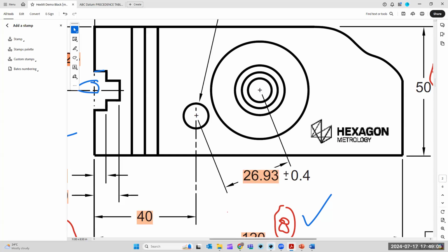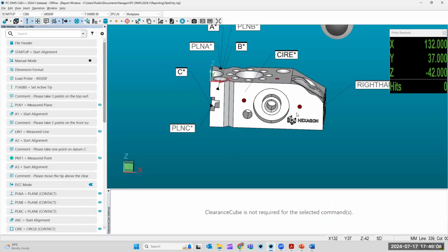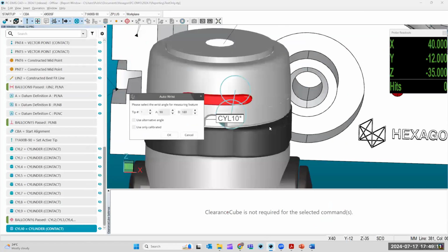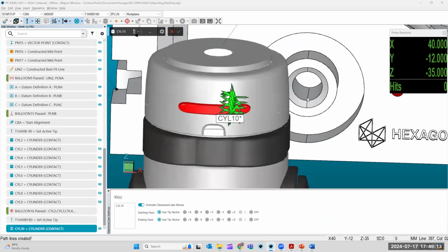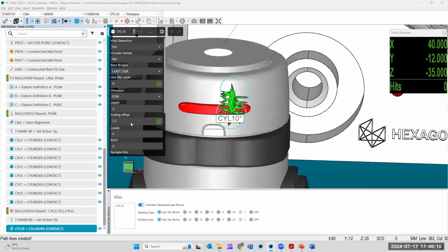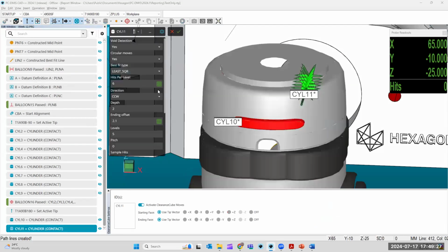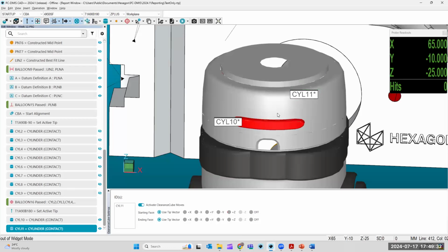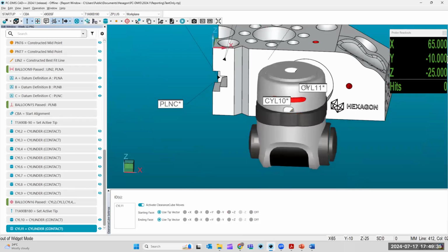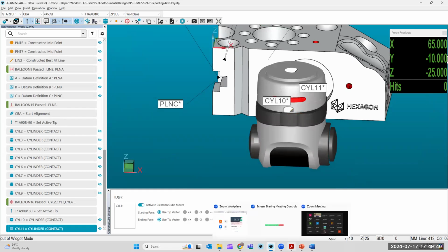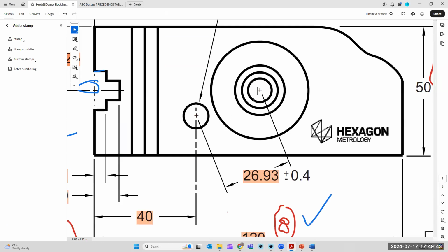Right now they don't exist, so we would have to build them. We go shift, and it's going to change the tool angle. We should know tool angles, and we should know our end offsets, so this is nothing new. It's just practicing. Click OK, and then we click our second feature. We change our end offsets to 3. Then we have cylinder 10 and cylinder 11, and we want the distance between them, because our drawing is just showing the distance between them.